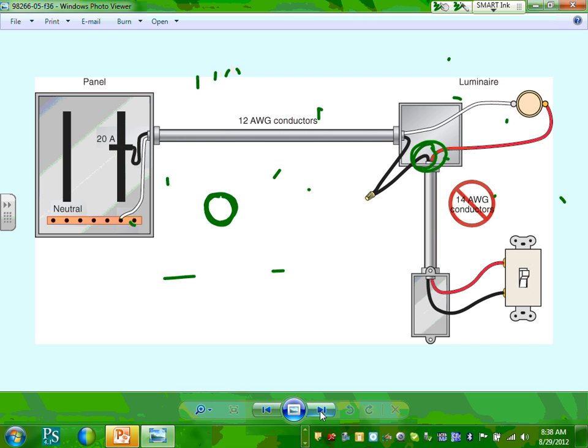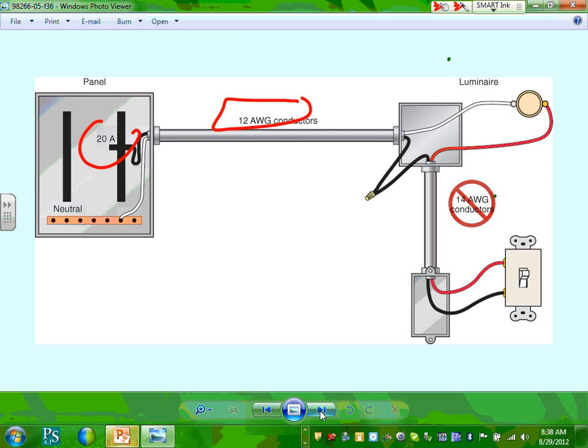Tab rules. Here's where I got caught one time. Jamie, my friend, I wired my brother-in-law's house, and he wants everything 120. He wants everything 20 amps. So I used number 14 cable here, and I came to the lighting fixture, but the switch is bringing number 12 cable. I use it as a home run, and between the switches, I use number 14-2 and 14-3.